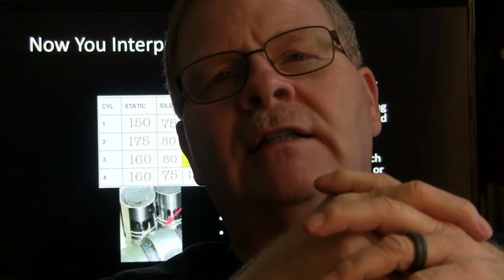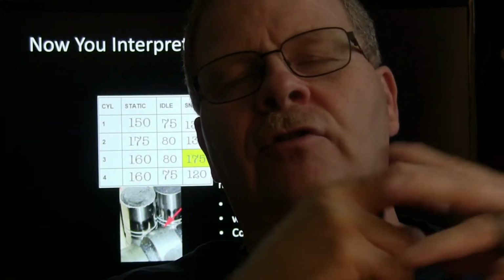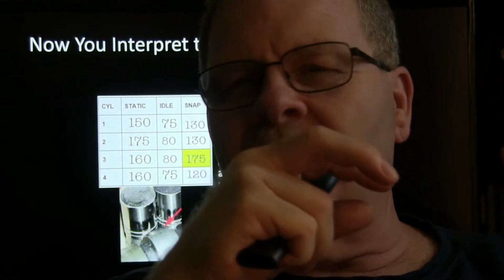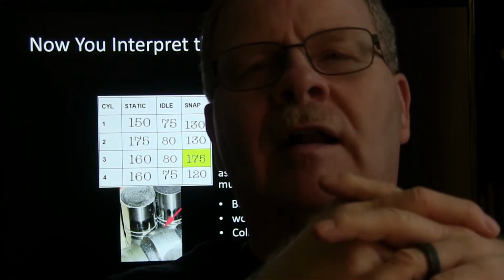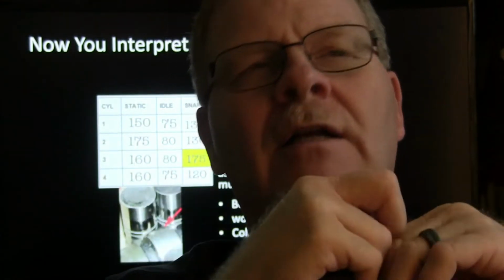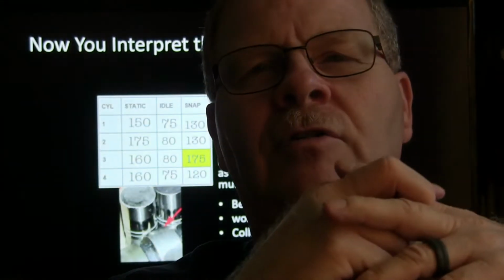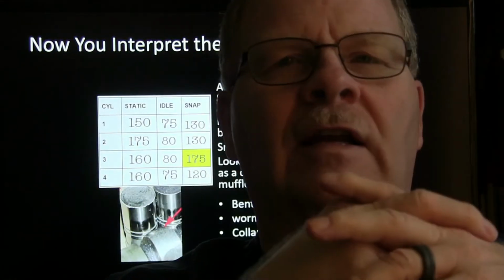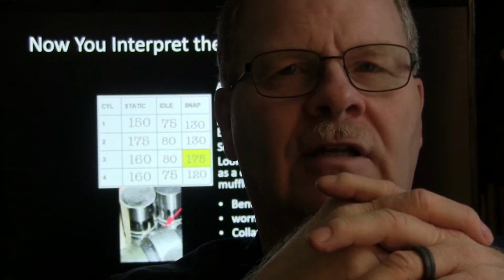The long and short of it is, anytime you tear one down, whether it's got roller lifters or whatever it's got on it, you need to look at those lifters very, very carefully. On the flat bottom lifters, you got to make sure they're not dished, and on the rollers, you got to make sure that the roller's in good shape and all that. To be perfectly honest, if you're going to do a good engine job, it's a good idea to throw a set of lifters in it anyway.